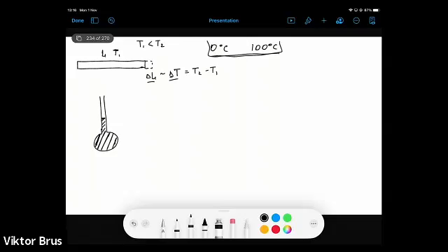Okay, so water is not the best choice, because we have this reference temperature 0 degrees Celsius when water freezes, and we want the liquid to remain liquid in the whole temperature range we work in. So that is an important moment. It should not freeze at temperatures within the range of those we want to measure.